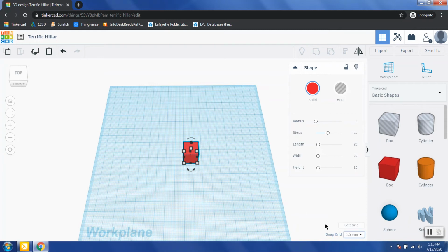You can change if you'd rather work with inches, but millimeters is what our software uses to actually run the 3D printers, so it's probably easier to work with millimeters and just use a unit converter if you're unsure of how big your object's going to be. We're making a keychain, so we don't want it to be huge, so I'm just keeping it at 15 millimeters.